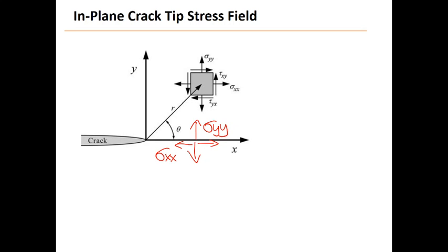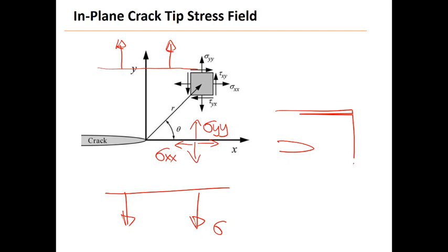And so if you have tension in the Griffith crack, you have basically tension away from the crack. So you apply the force here, and then same here. This is the applied stress. Now they are symmetric about theta equals 0. A case that would be anti-symmetric would be that you have a crack, your body is here, and then you have a shear stress that goes in opposite directions. Now this is going to be anti-symmetric about the line theta equals 0.